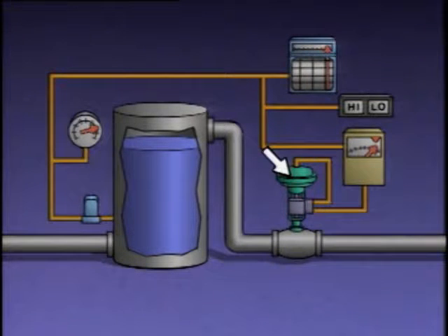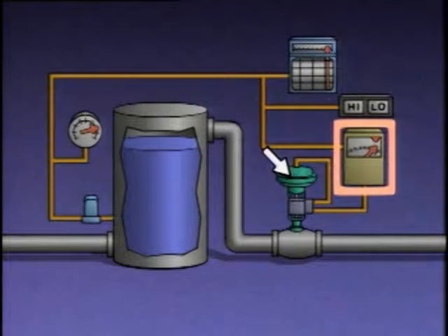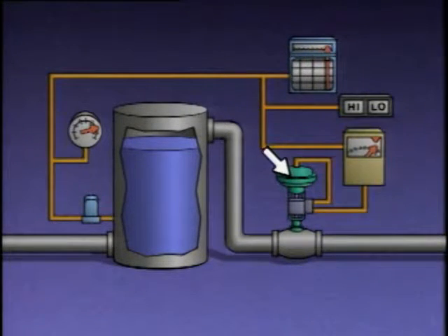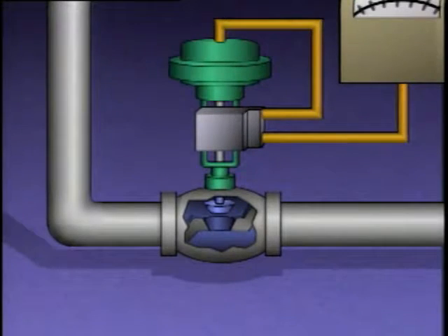An actuator is commonly operated by a corrective signal from a controller. However, in some cases, as in this pneumatic diaphragm actuator, the air pressure from the controller's signal alone is not enough to operate the actuator. To overcome the forces of friction in the actuator and the valve stem, and the fluid pressure against the valve disc, an actuator can be operated by a separate supply of higher pressure air. The higher air pressure is regulated by a valve positioner.